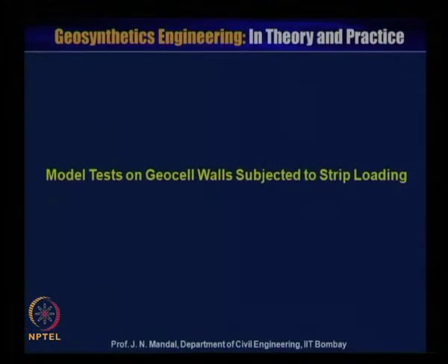So, you have to be careful in selecting the moisture content, so that the cohesion value can be reduced, the angle of friction can be increased, and the material can satisfy all other criteria, such as pH. This kind of fly ash can be used for a mechanically stabilized reinforced soil wall.